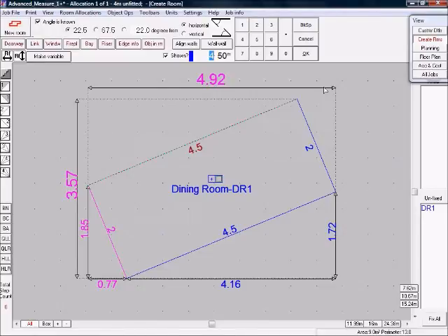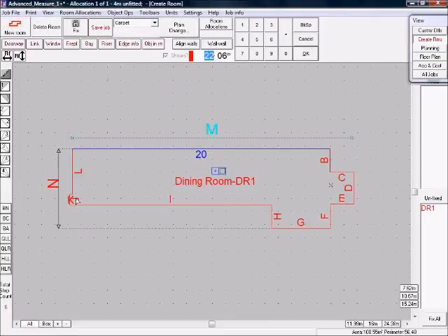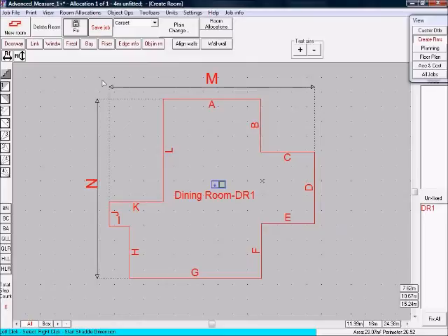Sometimes, when the shape morphs as you put dimensions in, you get into a situation where one variable wall becomes very short. For instance, if I have this shape here and enter this dimension as a lot larger, you can see that it has left this one all squashed up. It's difficult to click on a very short wall, but we can use the box zoom to zoom in on the bit we want to see.